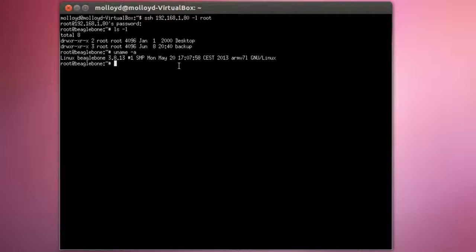The first thing that we're going to do is download the source code for the example. So I'm going to use git clone git. You can use git://, this is probably easier. I just want to show you that HTTPS is working too. I have that set up. I explain how to do that again on my blog. It's useful if you're writing to repositories more so than reading from them. This one is called bone device tree.git. So clone into bone device tree.